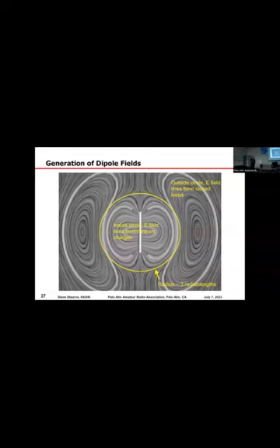So the wave gradually converts to a TEM, transverse electromagnetic wave, going away from the antenna. But that doesn't happen instantly, and it doesn't even happen at this boundary. It happens gradually as you move away. But by the time you're a few wavelengths away from the antenna, the wave has been formed, and you have a transverse electromagnetic wave that travels away from the antenna all the way out to infinity in principle.